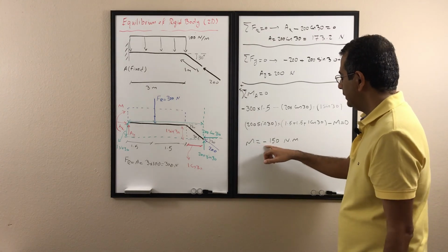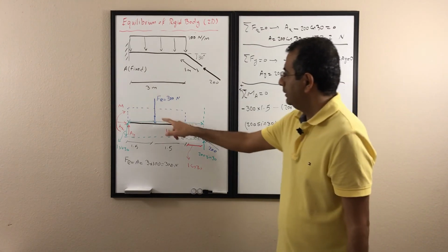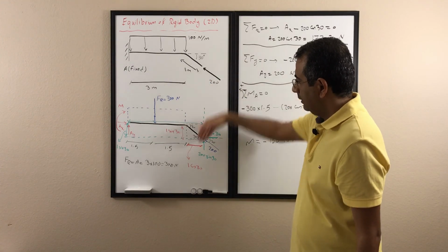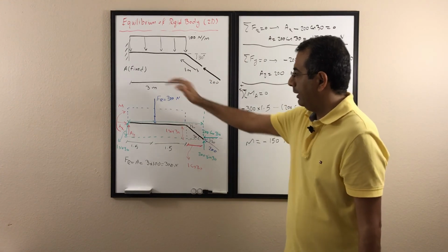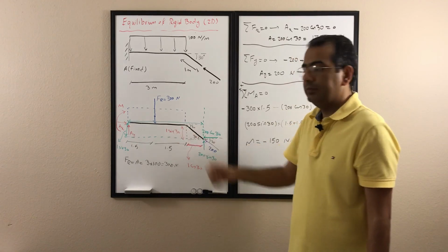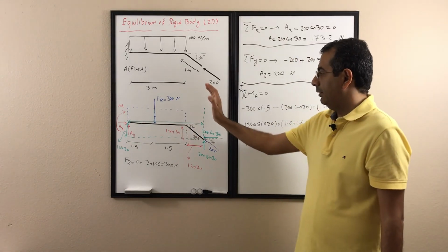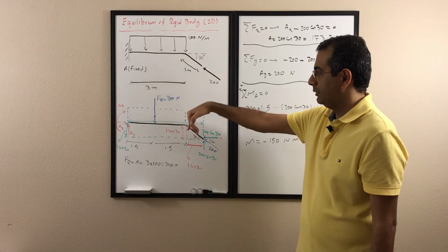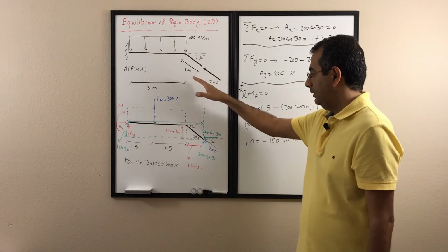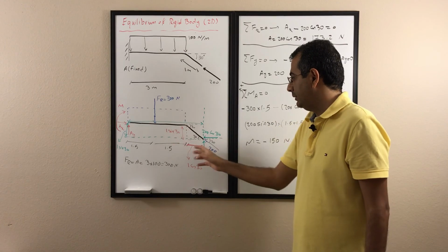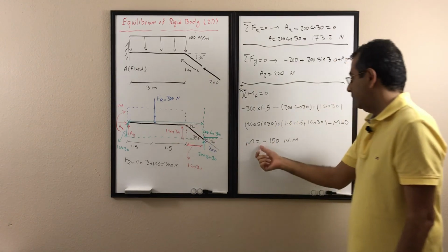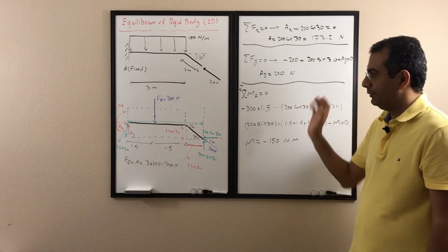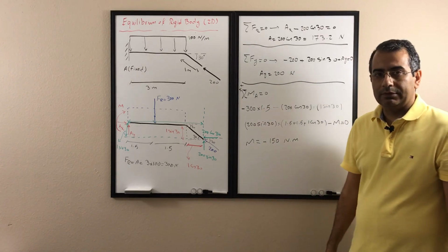And we could see it should come out negative, because these forces mostly rotate the object clockwise, so that M should be counterclockwise to hold it in place and prevent it from moving clockwise. So the M should be counterclockwise to cancel the clockwise rotation from these two forces. That's why we assumed it clockwise, it comes out negative, it means that it should be counterclockwise.